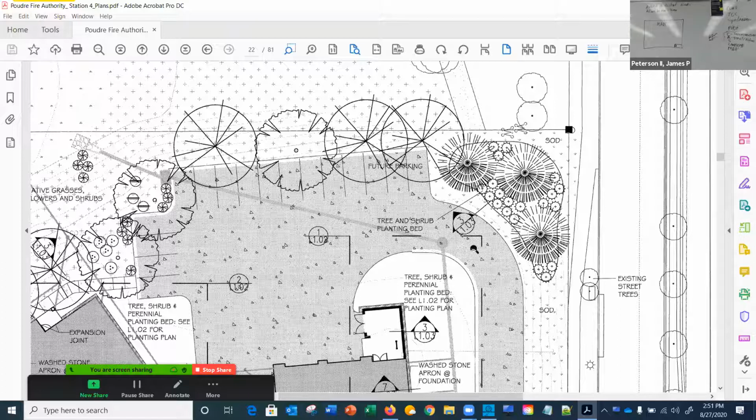What happens when it rains? And the water may go through some of the tree and the leaves, but then it might drip on the outside. They call that a drip line. Now, it's sort of expensive and time consuming to go measure the trunk of the tree and the drip line. And usually no one wants to pay a surveyor to do it. So do not count on that representing the real size. Some drawings do, some don't.